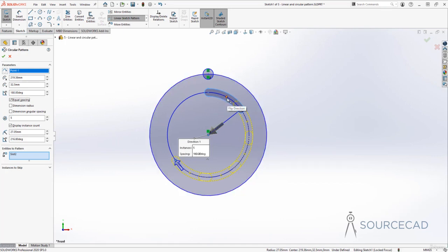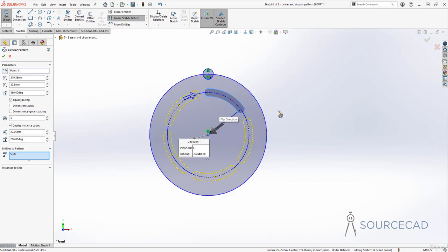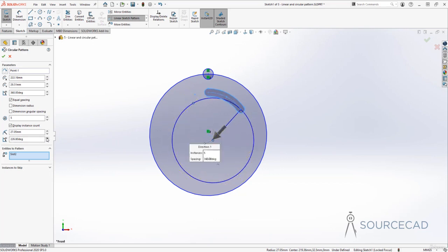So if you connect any corresponding points, for example, the center of this slot with the center of last slot, this will make a 180 degree angle. We want it exactly along 360. So I'll type 360 and press Tab key. Now this is actually the angle which this line is making currently in the array, which is 216.80 degrees from this exact point. So if you make a straight line like this and then start measuring the angle in anti-clockwise direction, and I accidentally clicked, so that deselected the object, that's fine. I'll just click on it again. This will bring it back. All right. So if you make a line and then measure this angle in this way, then the angle of this line will be 216.80 degrees. Changing this angle will once again change the center location, which I won't recommend. So I'll once again grab it and move it back.